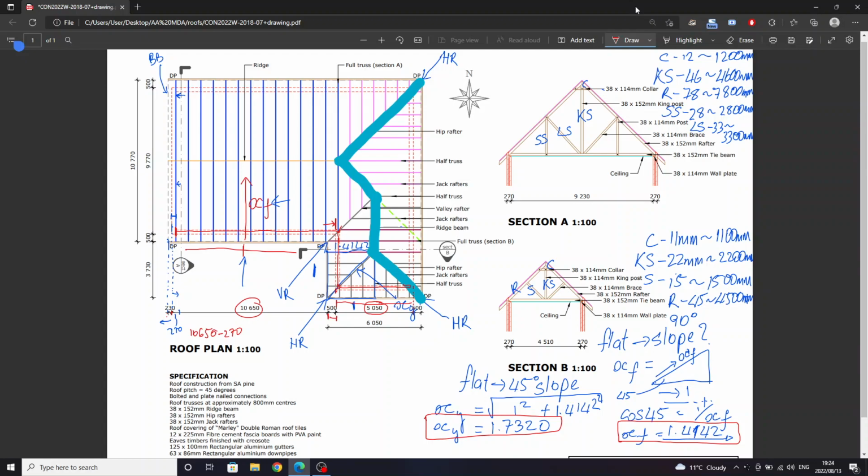You will. So this face I've covered. This length you'll find on this side. So you'll take 3730, which appears to be the end of the roof covering, right? And since we know that it's 500, you've got to subtract another 500 to get to your outer face. Okay, and that's just your outer face. So now you've got to come in another 160, I would say.